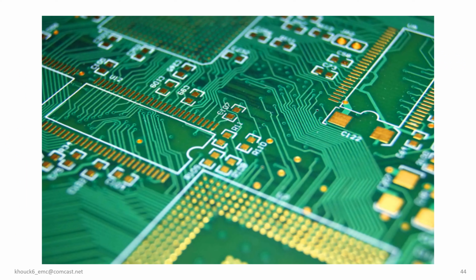Transitions in field flow within a printed circuit board can lead to reflections caused by various scenarios such as device switching, device drive, device input, reference transitions, or conversion of field energy to heat. These transitions adhere to 3 broad categories: fixed energy, fixed voltage, and fixed current. When transitions in the field path occur from a weaker relationship to a stronger relationship or lower impedance, a drop in measured voltage and an increase in measured current are observed. Conversely, transitions from strong to weak relationships result in the opposite effect.